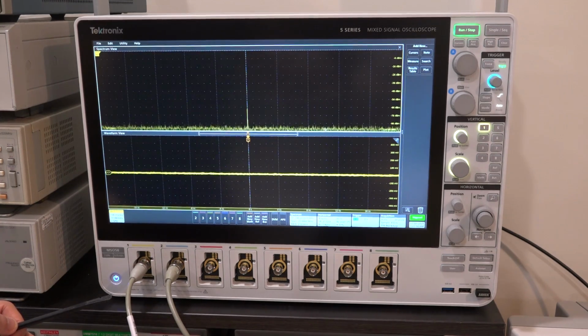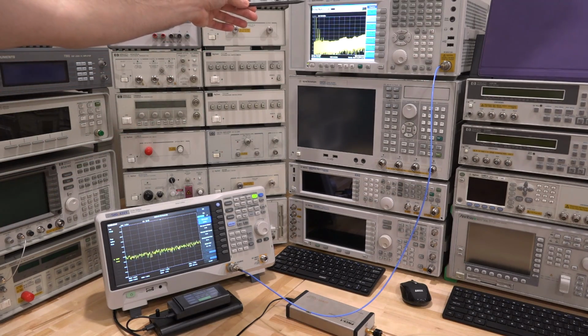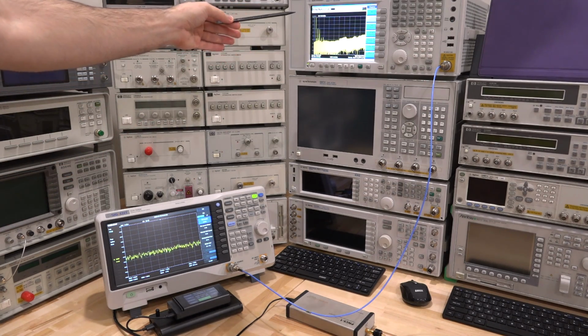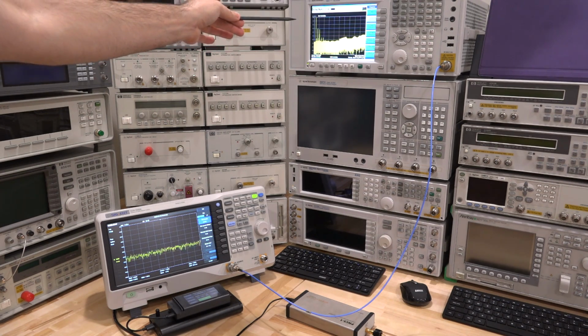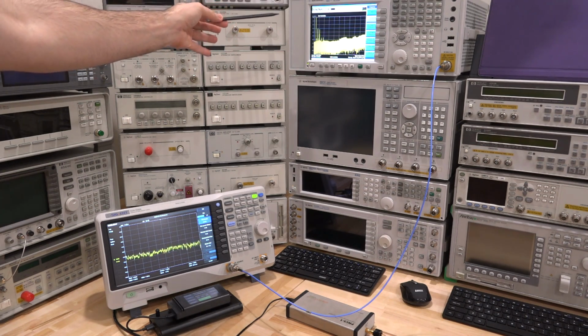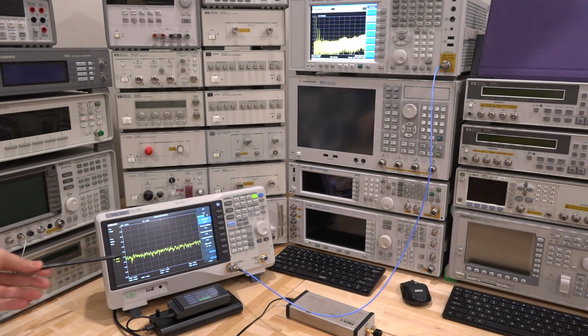So now let's go ahead and use a spectrum analyzer to measure phase noise. We're going to use the Keysight EXA at the very top. My MXA-B version is under repair and calibration, so we can't use that, but this has basically the same software. We can establish the performance the same way. And I'm going to use 3 sources here to measure their phase noise, and we can look at the characteristics of these 3 different sources.